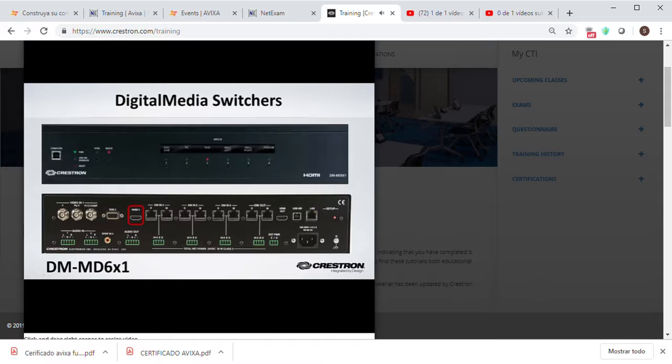Video input 3 is a digital video input through an HDMI interface that can accept HDMI, DVI-D, and DisplayPort multimode signal types. Audio input 1 and 2 are detachable terminal blocks for balanced, unbalanced stereo line level. Audio input 3 is an S-PDIF coax digital audio input. And inputs 4, 5, and 6 are DM inputs for connecting digital media copper transmitters from a remote location.